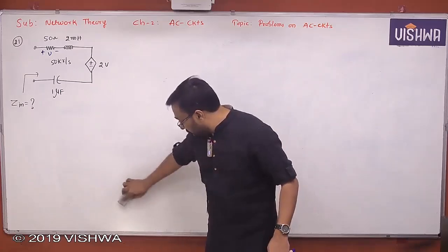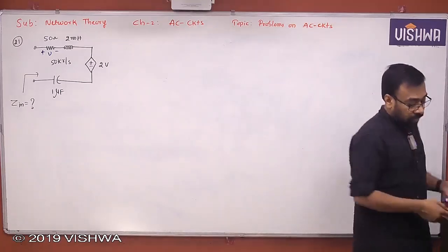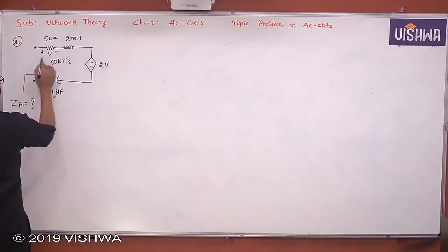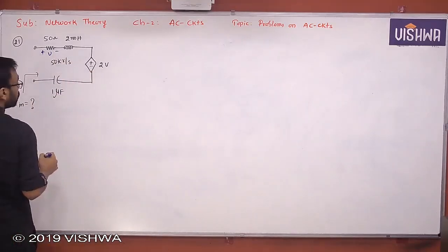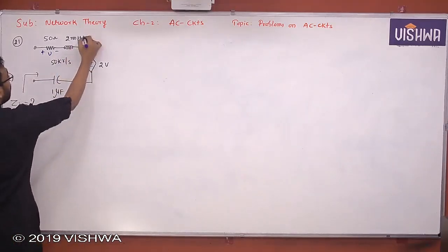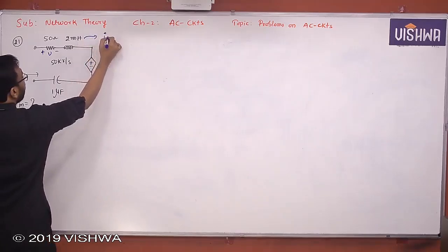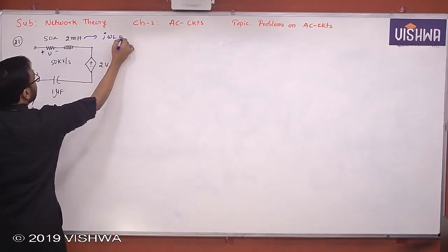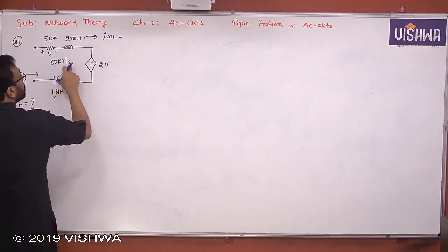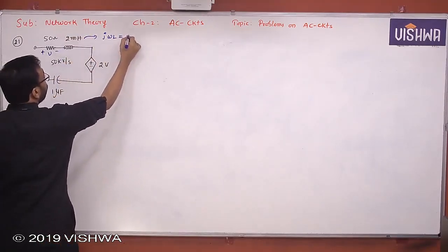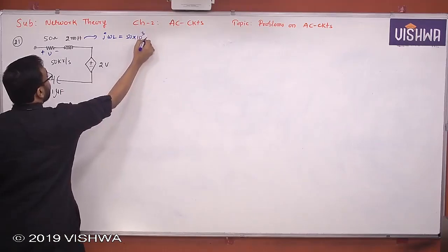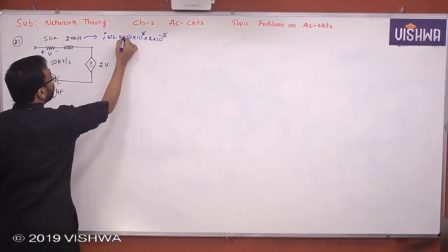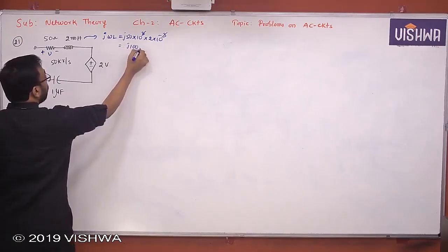If I apply the Thevenin method here, but before you apply it, make sure that all values are in ohms. So this is in time domain, right? Again, convert into complex. So jXL, j omega L. What is j omega L here? Omega is 50 kiloradian per second, and L is 2 millihenry. So 50 into 10 power 3, 2 into 10 power minus 3. So they cancel, and you get 100 ohm. So j100 ohm is the value.